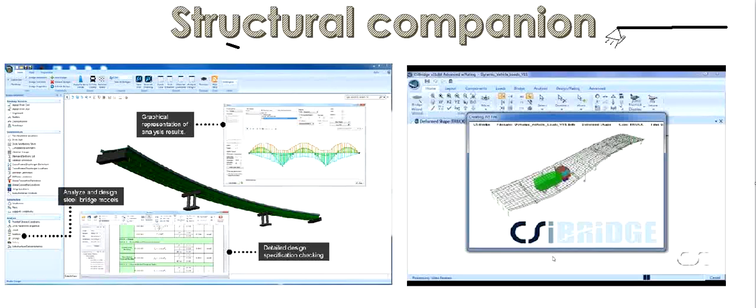Here you have your fixed support. Here you have your roller support. Then we have an applied load, a UDL. Now, to design this beam, you need to determine what forces are inside. What does it mean to design the beam? It means you need to determine how big the beam would be.